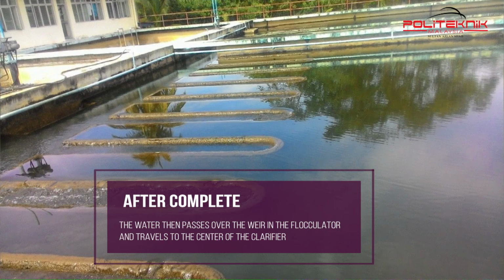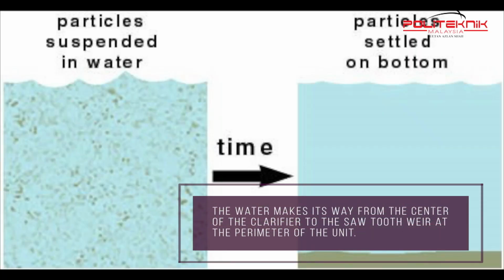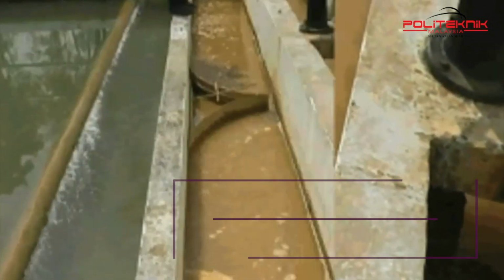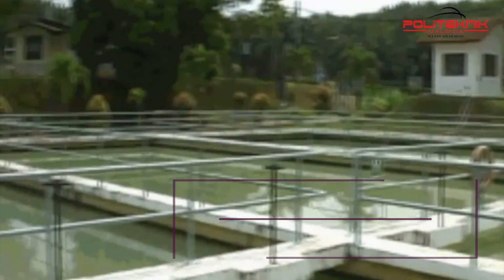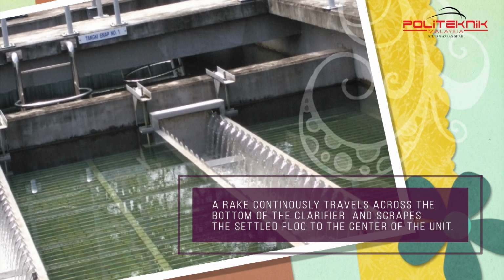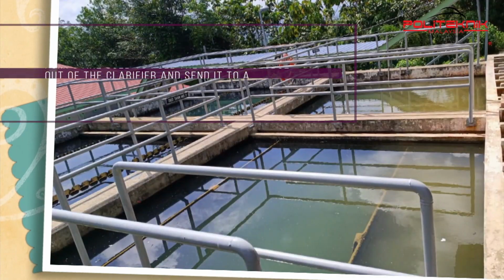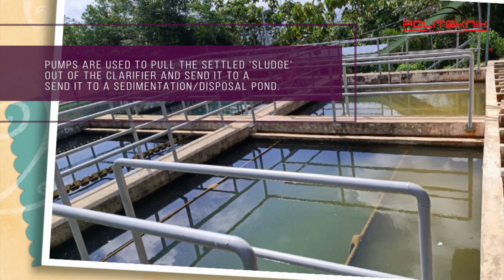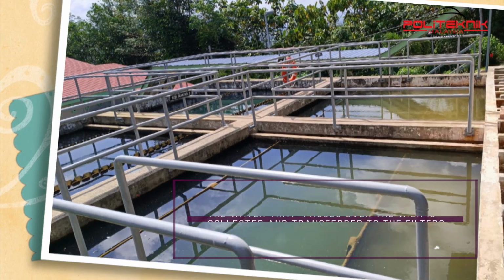the center of the clarifier or sedimentation basins. Here, the water makes its way from the center of the clarifier to the sawtooth weir at the perimeter of the unit. As the water makes its way towards the weir, the large floc particles are allowed to settle out to the bottom of the clarifier. A rake continuously travels across the bottom of the clarifier and scrapes the settled floc to the center of the unit. Pumps are used to pull the settled sludge out of the clarifier and send it to a sedimentation or disposal pond. The water that passes over the weir is collected and transferred to the filters.